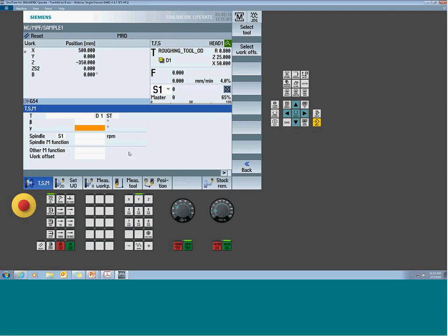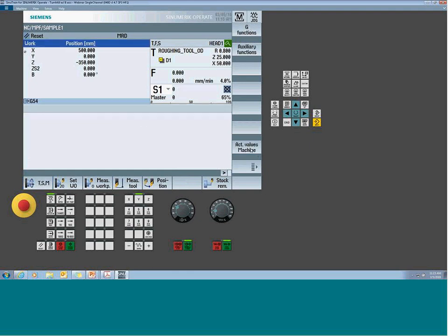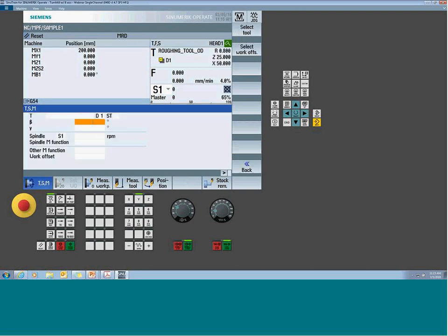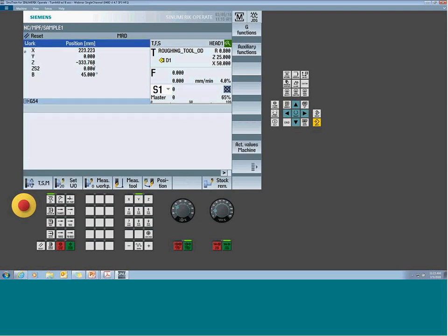So if I'm sitting back here at 0 and I look at my actual values, and I swing the system down, the actual values show what the motors are doing. I swing it to 45. The display doesn't change. But this did recalculate. That's how we track, and we can automatically adapt for however I decide to set this tool. And it's driven by the fact that we have the cycle on currently on this machine. That's what's tracking these numbers. This is our dynamic fixture offsets.